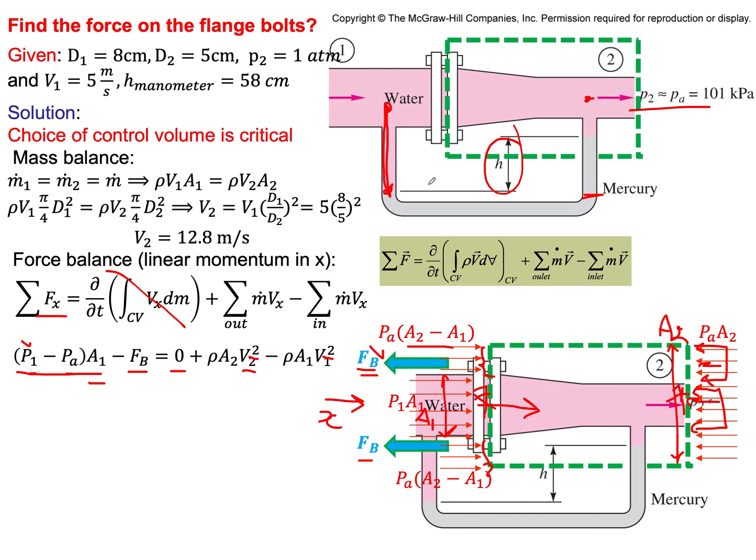take a constant height, because you're in the same liquid at a constant height, that pressure over here is equal to that. Then as you go up you subtract the pressure of the mercury and then the pressure contribution due to the water, so you end up with pressure P1 minus P2. And P1 minus P2, with P2 being P atmospheric, is just the density difference between mercury and water times g times h, this h.